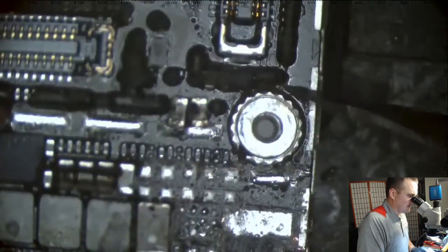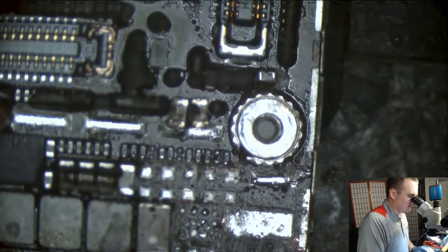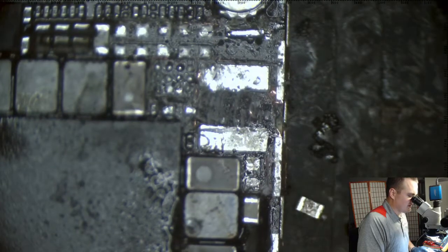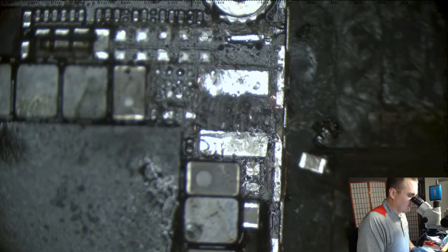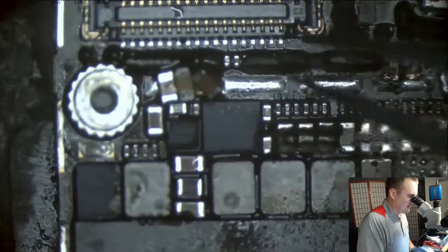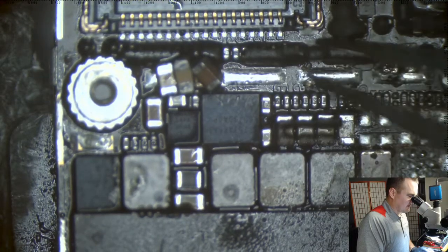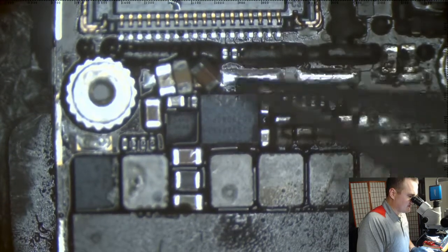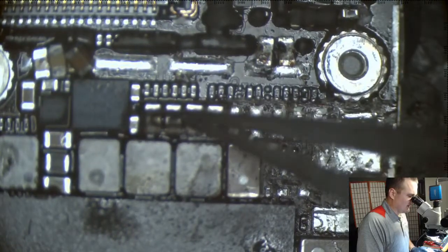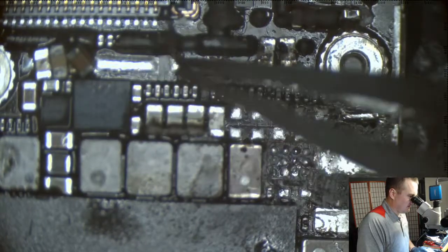And when these little caps and filters and resistors melt inside the solder, just like this one did, when the solder melts inside the underfill rather, they pop loose. So yeah, that's a nightmare when that happens. And if it does, on many occasions I have replaced this entire row underneath the proximity connector, resoldered the whole thing because it all came loose. It sucks, totally sucks. But even as sucky as that is, I can't bring myself to peel away all this.